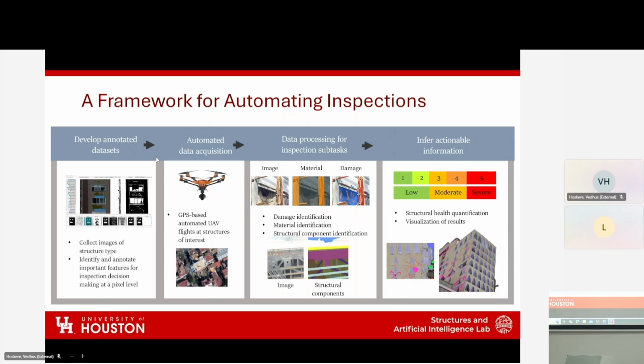After you do the alignment, that's when I would do the GCP and control points. After that, I do the densification. It's called normal. If you go to mesh, or go to mesh model and normal detail. So that's how much detail you want in your densification.